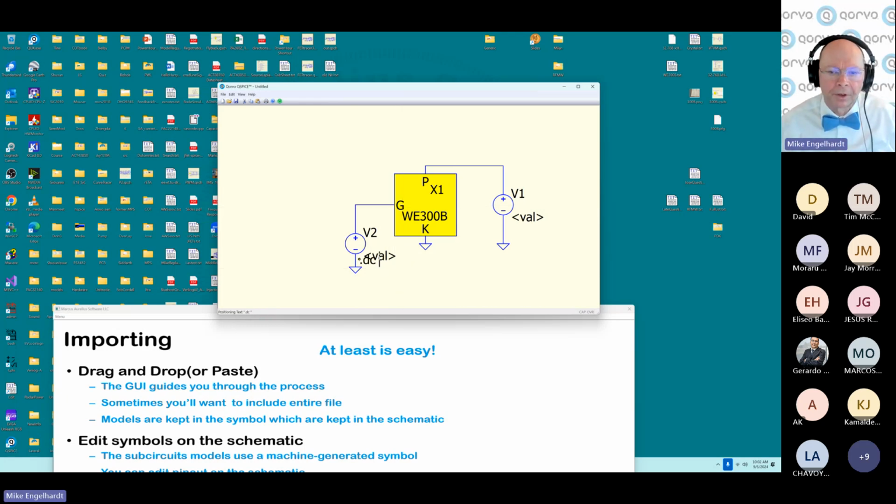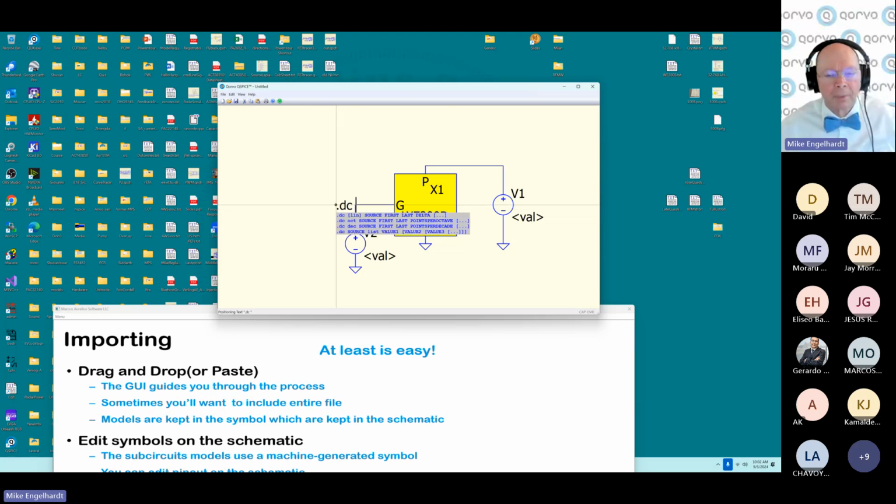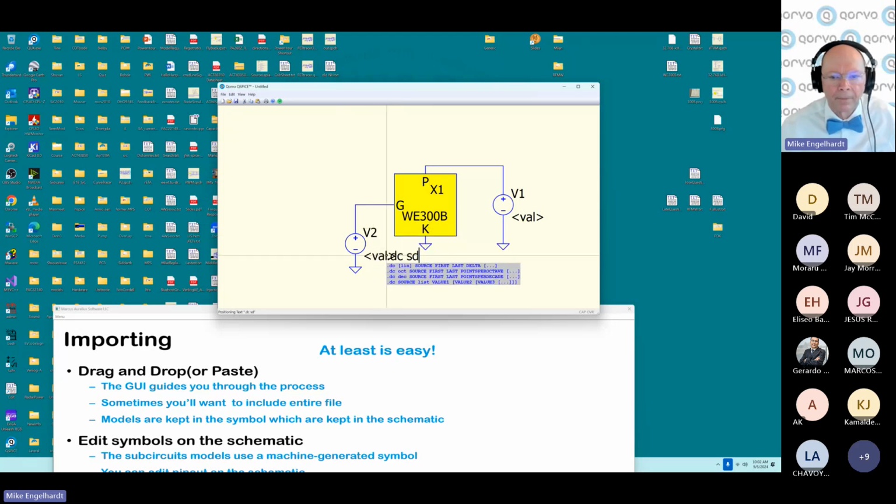One thing about the user interface here. I said that there was no dialogue, so everything was edited in place, including the SPICE directives. But a lot of times people would want the dialogue for a SPICE directive because it gives you a form to fill out, and you don't need to know the syntax. Well, you can see underneath where my mouse cursor is in this editor, it's giving me the hint. So you have fewer dialogues, but more hints.